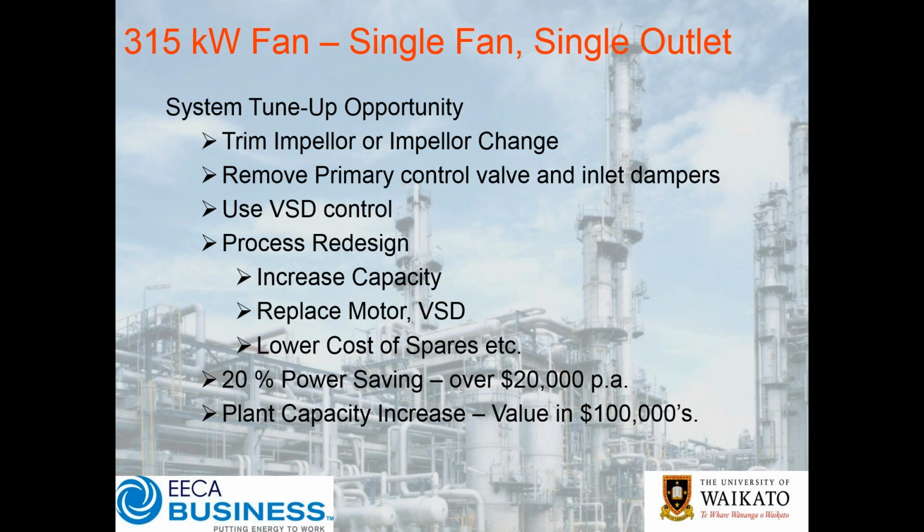It really does depend on the pressure flow mix that you're looking for. But typically, if the impeller's undersized or oversized, you're not so much changing fan type, but more just getting the right sized impeller.